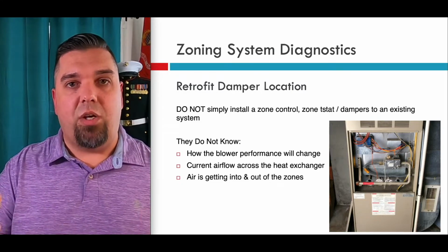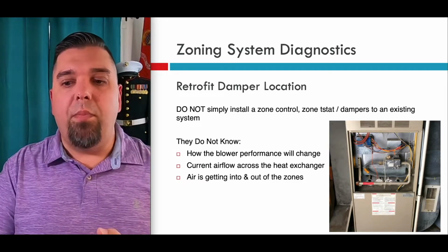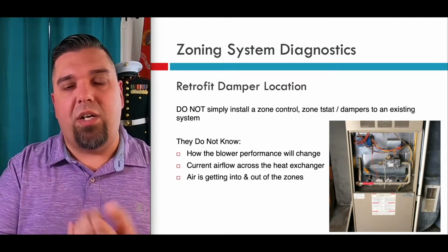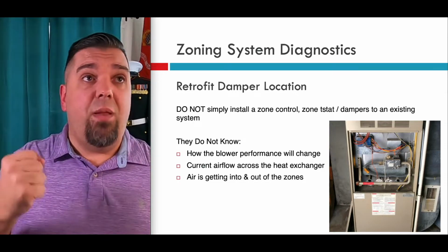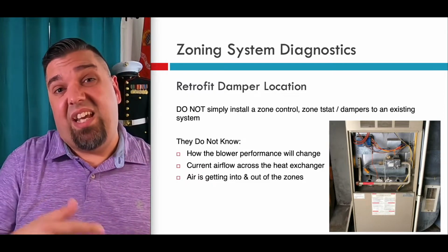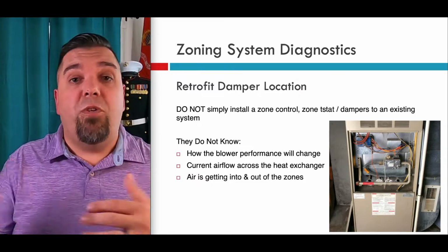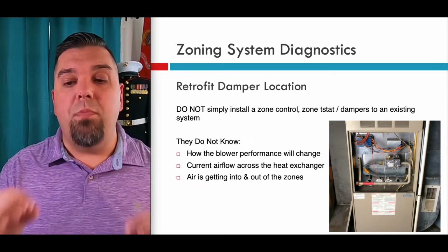When they test the ductwork, they can actually do duct blaster pressure matching and see what is actually moving through that duct blaster to fill that ductwork. And then other people will just measure leakage and then measure the actual output of the air at each register with, let's say, an Alnor hood, and then they'll know the difference is your total. So there's many ways to measure it. The key is that you measure it.